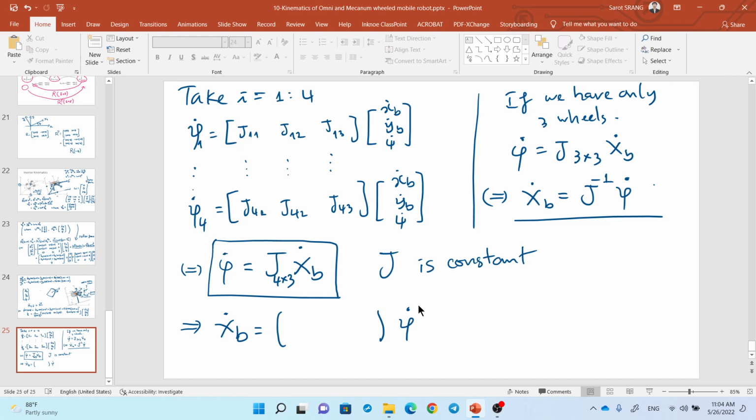So it's the same thing as if the fourth wheel rotates properly, has velocity properly, then we have a solution. So let's say if you just control velocity without thinking about kinematics, you know all the phi 1 dot, phi 2 dot, phi 3 dot, phi 4 dot, and then you want to calculate where the robot goes, right? You don't have the solution, but you can have the best answer.